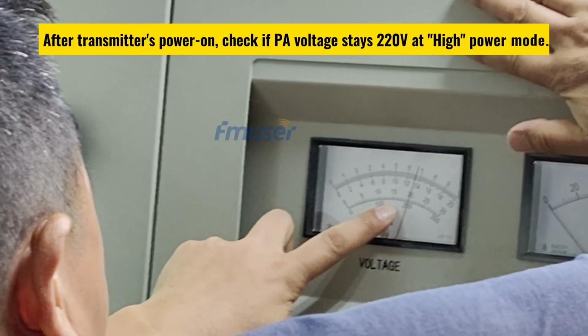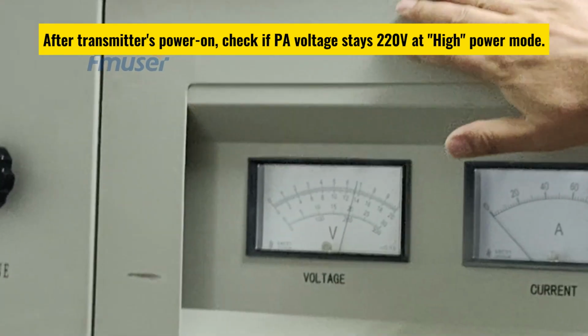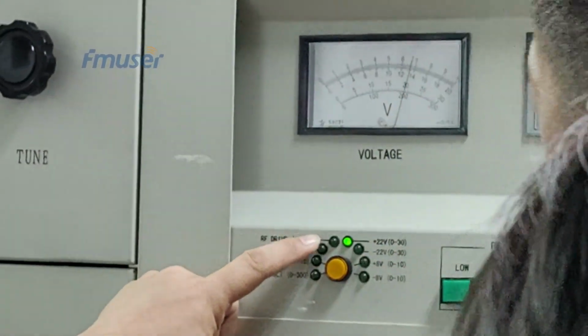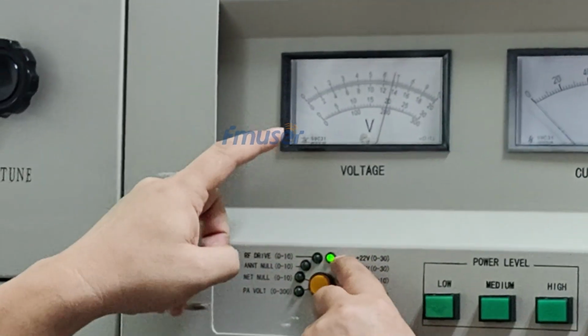After ensuring that the power is turned on, check whether the power amplifier PA voltage is 220 volts in high power 10 kW mode. Click the yellow button on the left and select PA volts. The indicator light will illuminate to confirm your selection.